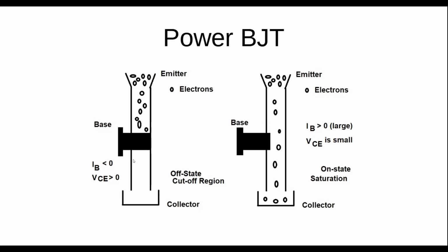It's the same thing on this side. Although this is closed, I've shown it as closed, you still have a little bit of current that sneaks in. That's the so-called leakage current, you remember. So even in this case, even with cutoff, there's a bit of power dissipation. It's much smaller than the dissipation you'd find when the device is operating, when it's on or in the saturation region.